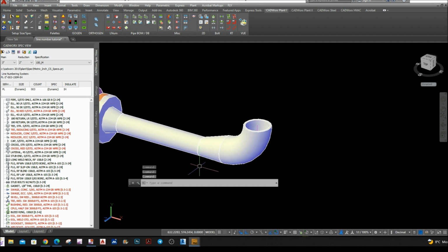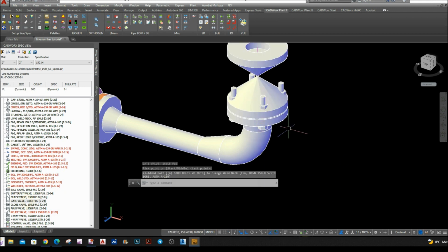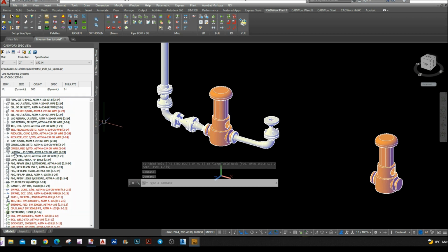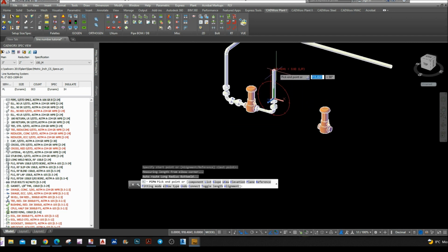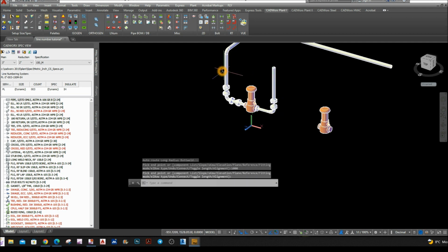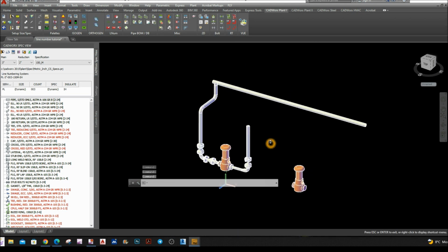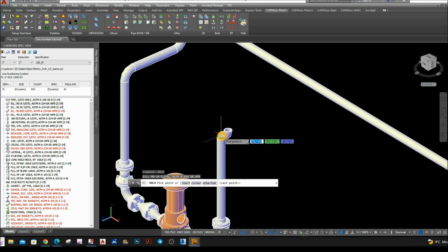And then from there, I'm gonna attach a gate valve from this in point, and then add a flange from this in point. Add a pipe from this in point and a pipe with the same size or the same length, and enter again with this one here, and then add elbow from this in point and point it along the y-axis.